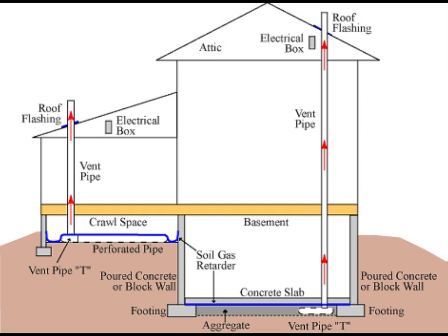Radon venting. Gravel. Use a 4-inch layer of clean, coarse gravel below the slab, also called the foundation. Plastic sheeting or vapor retarder. Place heavy-duty plastic sheeting, 6 mil polyethylene, or a vapor retarder on top of the gravel to prevent the soil gases from entering the house. The sheeting also keeps the concrete from clogging the gravel layer when the slab is poured.